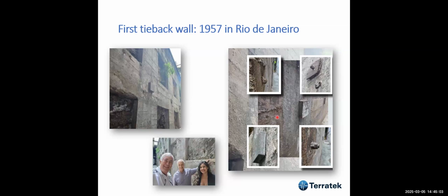Because Professor Nunes used to tell us that the Germans were the second to use this kind of technology, but they used it 1 year after this experience. And the wall, of course, presents signs of corrosion, as I've told you. In those days, they didn't make any corrosion protection. And these were usual concrete reinforcement bars, 25 millimeter in diameter. And everything was new here in 1957.